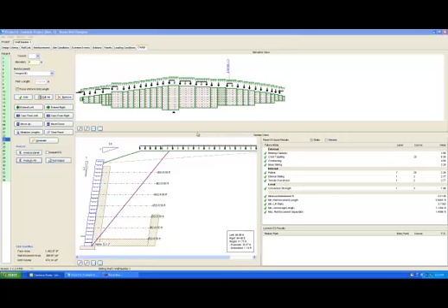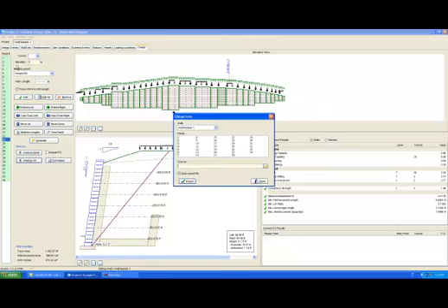That's it. Our design is complete with respect to internal, external, and local stability, as well as internal compound stability for both static and seismic conditions. If this wall requires a global stability check by the geotechnical engineer, Vespa is equipped to create an export file that can be checked by the global stability program GSlope, which is available through mitersoftware.com. To export this file, simply go to the File menu and select Export to GSlope. You can then pick the wall and the section or panel you want reviewed. The GSlope file will contain the wall geometry, soil conditions, and loading conditions.